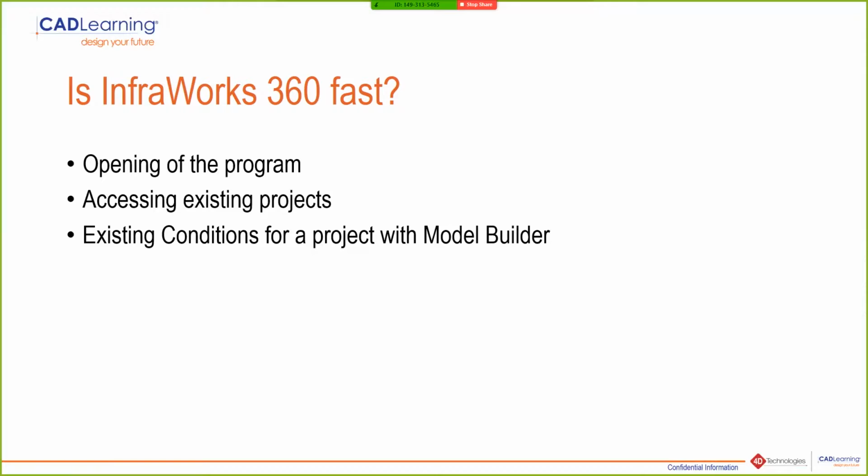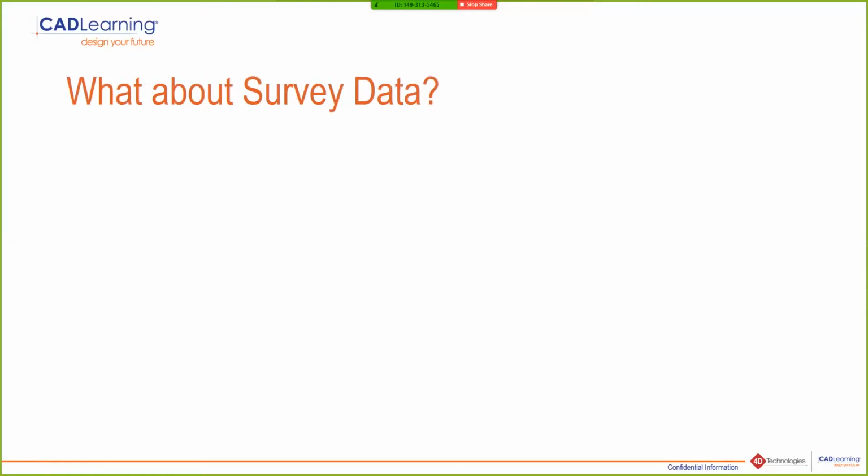Other things to note when you're in InfraWorks, you can get existing conditions for any project from their model builder feature, which can take, depending. I did one this morning, it took 2 minutes. I zoomed in using model builder to my location where I wanted it, created the file, and it took 2 minutes to get back to me. It sent me an email, even told me it was ready. So 2 minutes later, I've got this little tile, it's ready to click and go, and when I open it, it's wonderful.